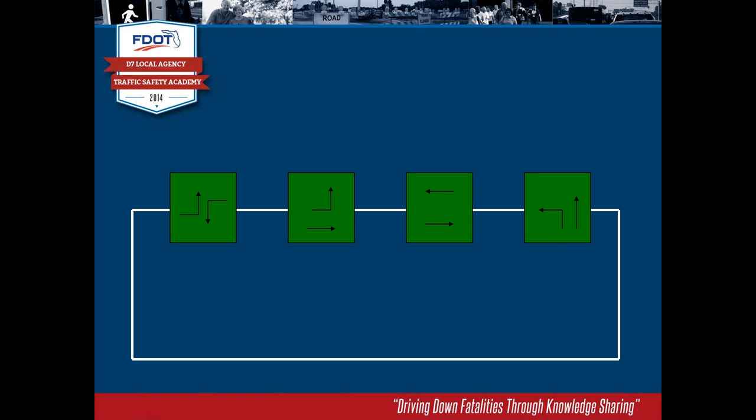We said it was heavier, so eastbound continues, westbound gapped out, and then the eastbound through will start because the westbound left had gapped out. And so that's what will occur then. And then once the eastbound left either gaps out or maxes out, we'll have the east-west through operation.